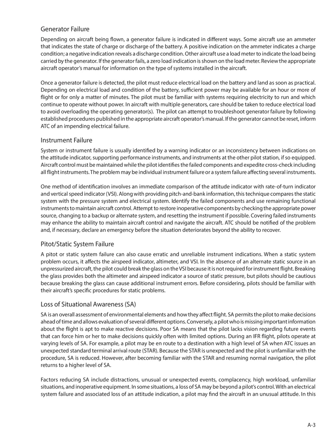Attempt to restore inoperative components by checking the appropriate power source, changing to a backup or alternate system, and resetting the instrument if possible. Covering failed instruments may enhance the ability to maintain aircraft control and navigate the aircraft. ATC should be notified of the problem and, if necessary, declare an emergency before the situation deteriorates beyond the ability to recover. Pitot/static system failure.